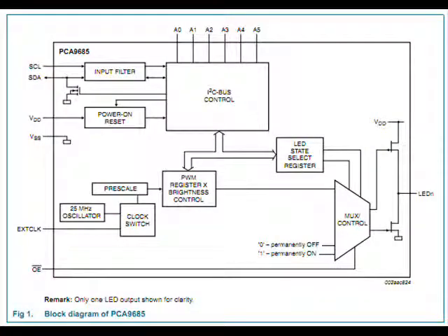And the reason for doing all this is then I might be able to get more heat out of the LEDs and spectral content during the nighttime operations. Maybe to the point I wouldn't even need to use a nichrome wire heater in the base plate of the greenhouse. Don't know, but a lot of things to look at. And the chip I'm looking at using is a PCA9685. It's a 16-channel 12-bit PWM controller, and it's really cool for this application because I can use many of the channels for LED control, set aside one for purposes of controlling the resistive wire heater, that is if I need to use it.